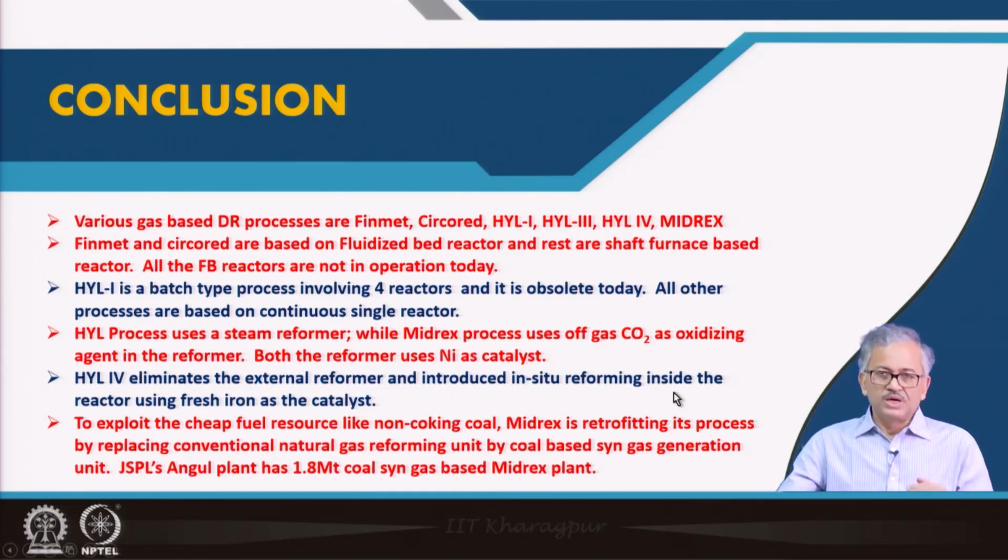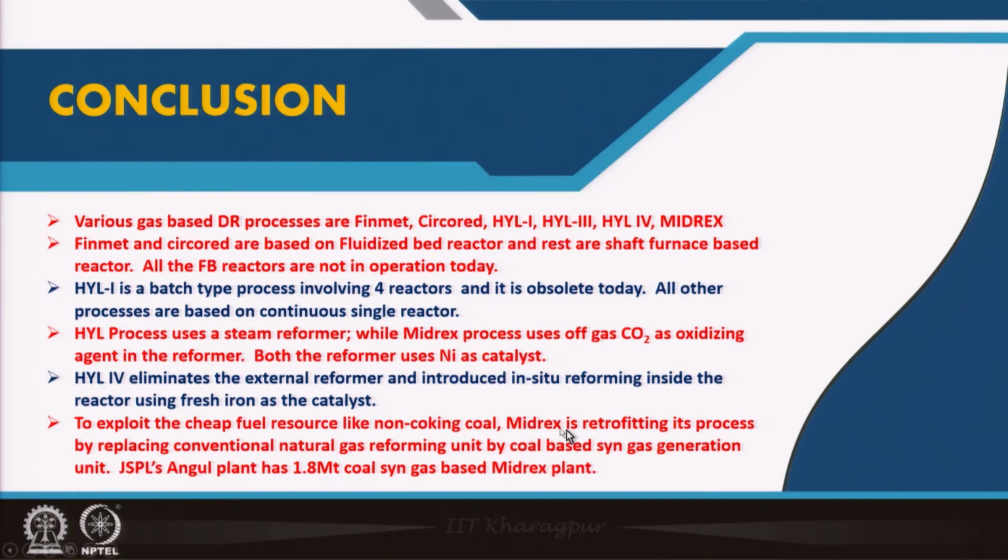So this is a new direction to utilize the non-coking coal, especially in India where we have a large reserve of non-coking coal. We can use this type of reactor; it is welcome in our country. In a gas-rich country, they can obviously use the gas-based reforming unit, but in our country, with non-coking coal and a scarcity of coking coal, we must go for this type of unit, where you can use the syngas generated by coal gasification.